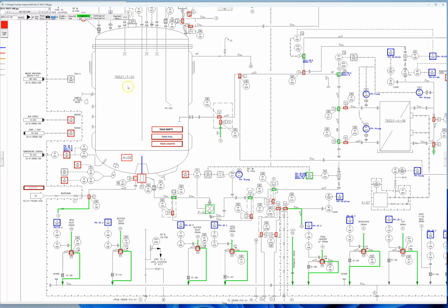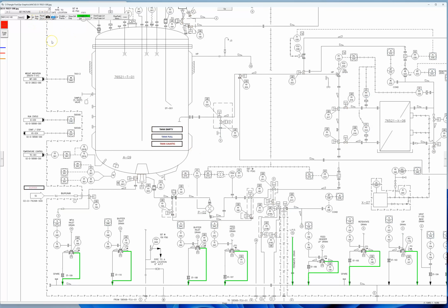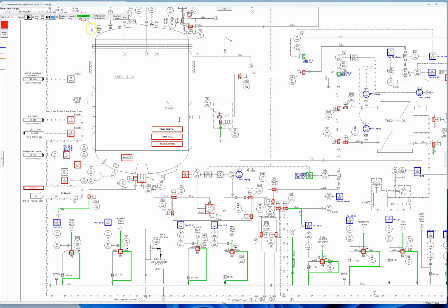So what also is good is to show the differences. So let me reset, and this is useful when you have flow paths where you change the CMs to different states, and you don't know, because there's so many pieces of equipment there, what got changed. So what this does for cases like that, you select this, show all differences only. So you'll basically show the difference from current to the next one.